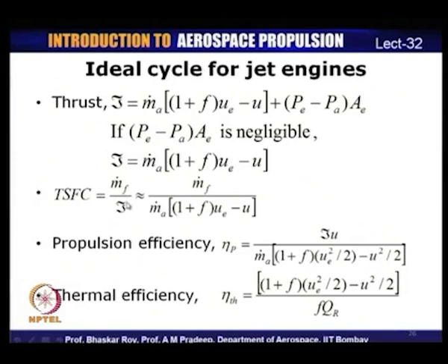TSFC is equal to m dot F by thrust, and similarly the propulsion, thermal and overall efficiencies, because we now have all these parameters which are known from the cycle analysis. So, this is primarily the cycle analysis process for a turbojet engine without any afterburning.